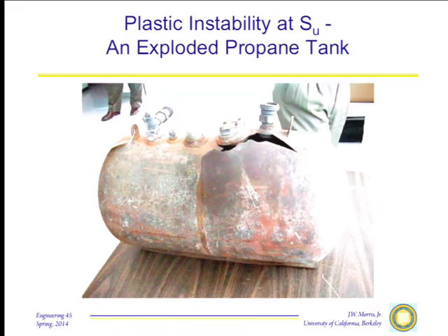You know this was caused by an expansion of the liquid because you have this relatively small fisheye failure. You have a liquid, you expand it so that the force gets big enough to exceed the ultimate tensile strength in the tank, usually some weld, and it's going to blow up. But the minute it fractures, the minute the volume has a chance to increase, the pressure goes away because the compressibility of the liquid, even propane, is pretty small.